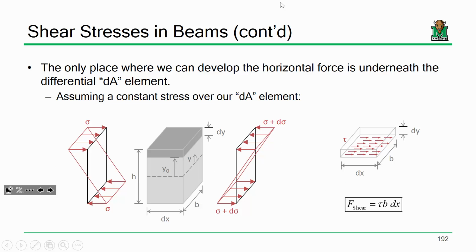So if I cut this off and I look in here, just like the pages of that notebook that are sliding together, if I glued them, they wouldn't be. Why? Because they developed some stress. I propose that there is some shear stress acting along this plane. Make sense? Now that stress I'm going to assume is uniform. I'm going to say it's the stress over the area. What's the area? B dx. Sound good? I propose that that is the force developed by shear along that plane.